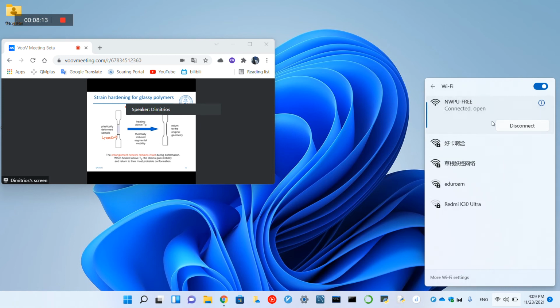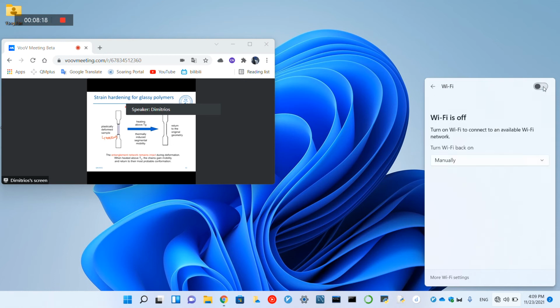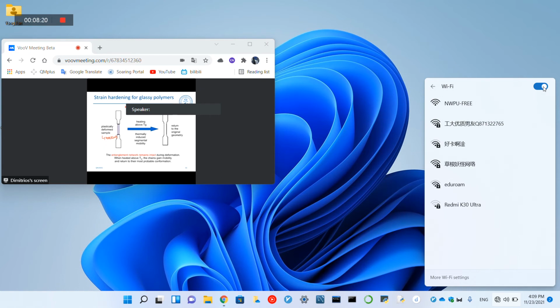If we heat the polymer above the glass transition at this stage, so we stop applying strain, and we obtain this sample which has the neck here. And we said that at the neck, what is the situation of the chains? The situation of the chains is that they're getting oriented progressively, okay?